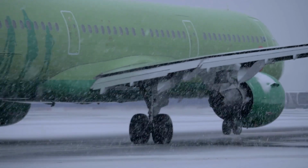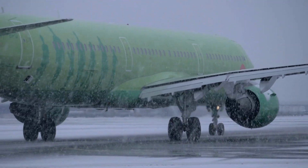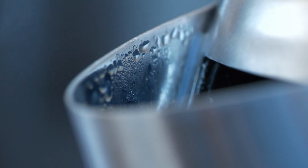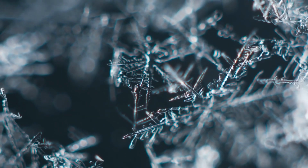During cold weather operations, special attention is required when performing a preflight inspection. The crankcase breather lines may become clogged with ice. When the crankcase vapor cools, it may condense in the breather lines and subsequently freeze, causing a clogged condition.